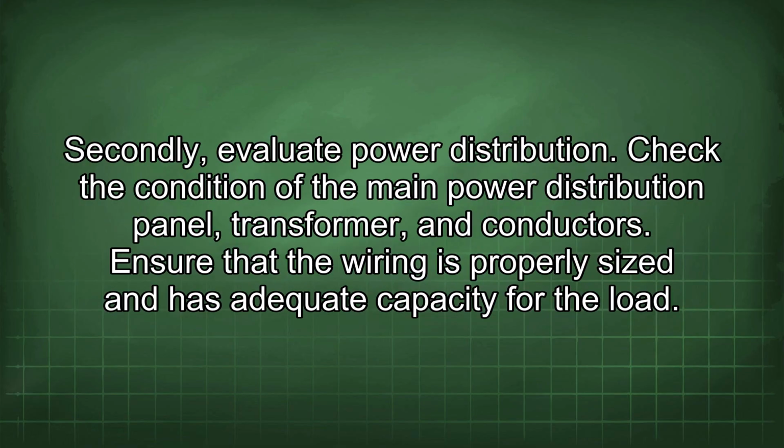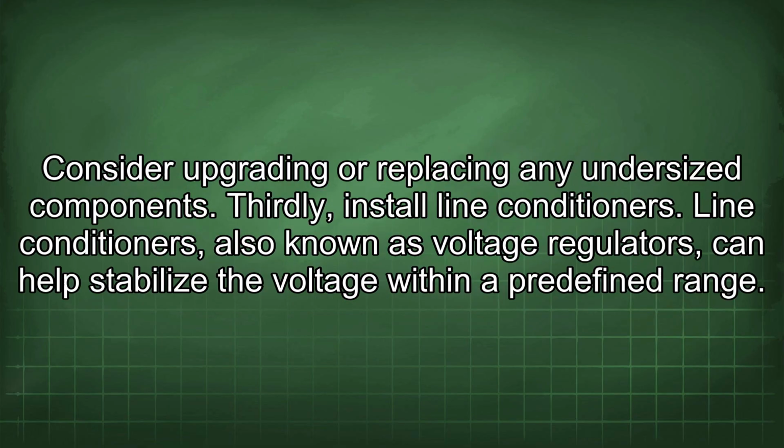Secondly, evaluate power distribution. Check the condition of the main power distribution panel, transformer, and conductors. Ensure that the wiring is properly sized and has adequate capacity for the load. Consider upgrading or replacing any undersized components.